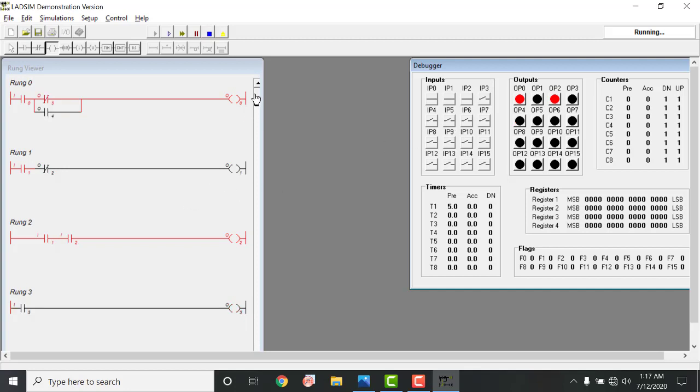And after that, our fourth input, sorry, here by clicking on input 4, another solenoid valve will push that material, because that would be an imperfect assembly. So input 4 is showing output 5. Yes, exactly, output 5, because input 3 is connected with this output 4. So you can easily see how we can play with these simple switches to control our simulation.